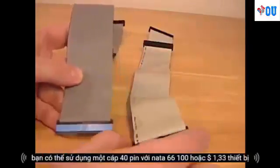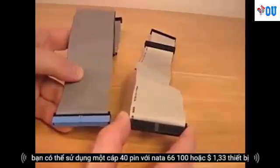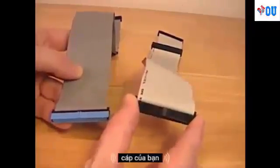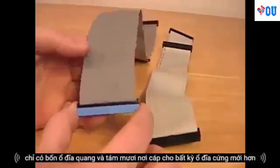You can use a 40-pin cable with an ATA 66, 100, or 133 device, but it won't run at the fastest speed. So it's recommended to use these cables, the 40-wire cables, only for optical drives, and the 80-wire cable for any newer hard drives.